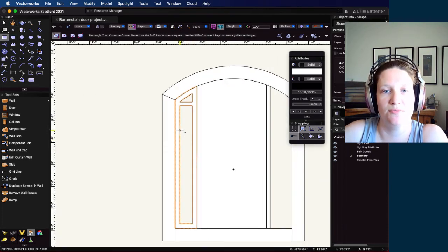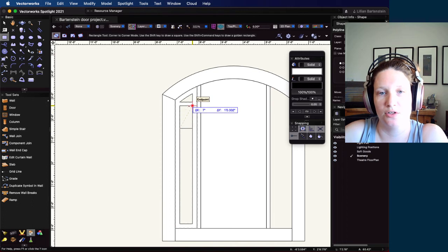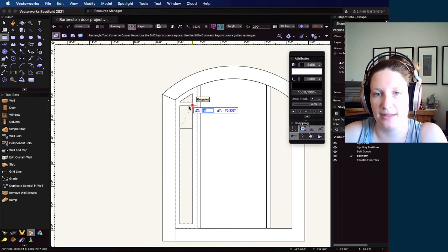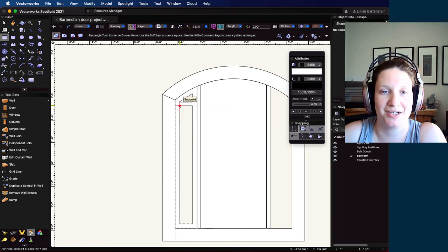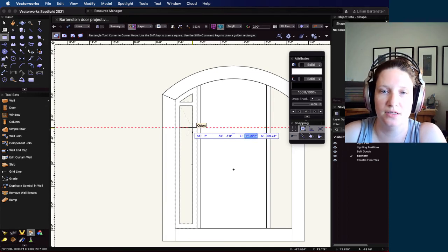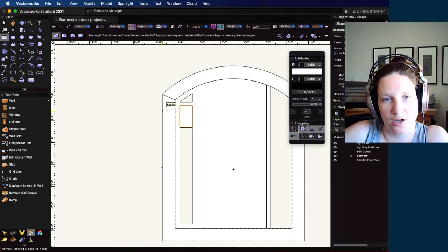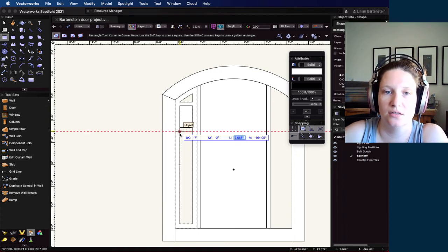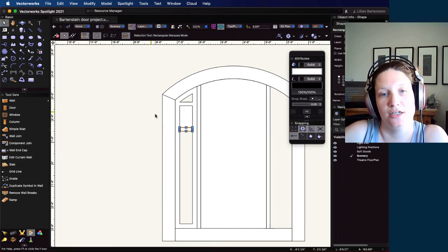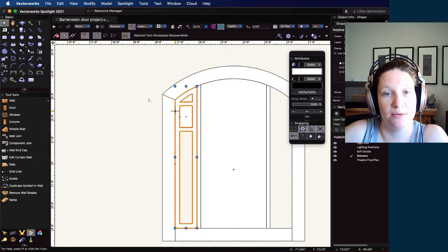And I'll do the same thing with a couple more little rectangles, right? So let's say I like this sort of 1 foot height here. I can click, let me hit escape to get back out. I can click up here, I can leave it at that 7-inch width, and I can use the -1 foot in the Y dimension, make a 1 foot tall rectangle, then I can make a little 2-inch rectangle after that, right? -2 inches, click, and I can continue adding those 2-inch rectangles to that outside trim using add surface, all right? So let's do maybe one more of those.